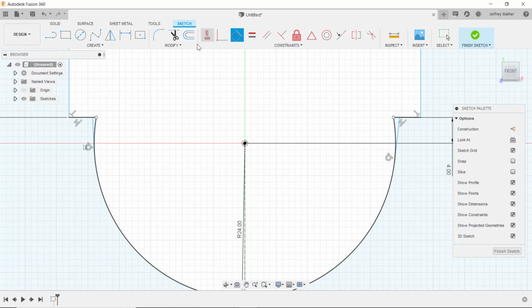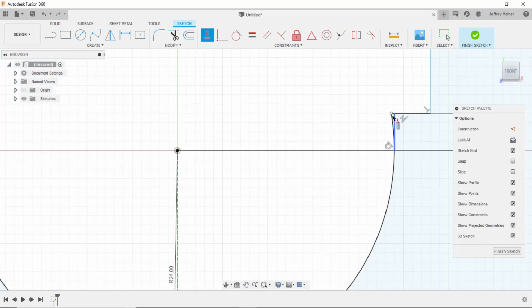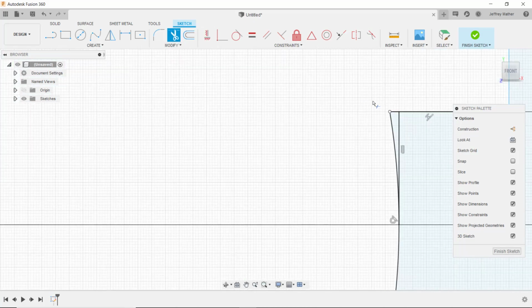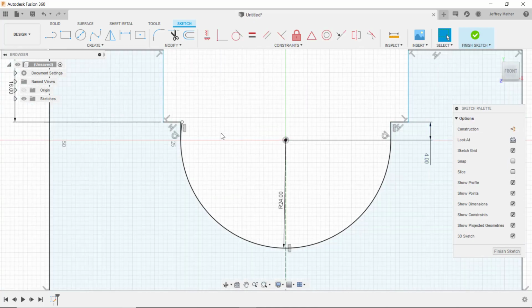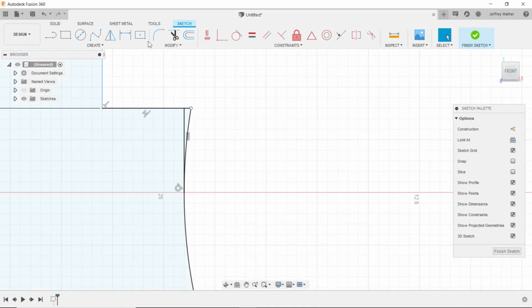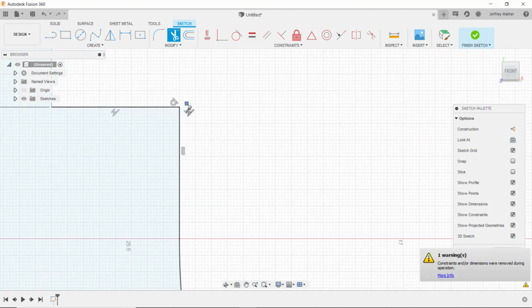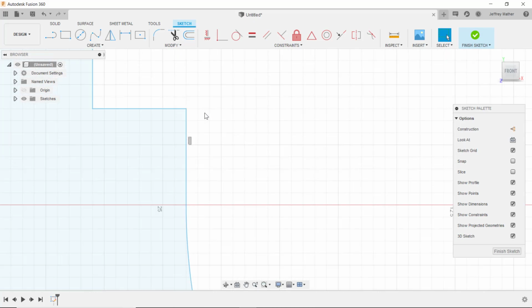And then I want those lines to be vertical, so I want that to be vertical, and I want this to be vertical. And then I need to trim out this little piece right here and this little piece right there. There's some geometry that's left here that I'll delete. And so I see that this turns black on this side. I'll trim it on this side. And I see there's some geometry left over, so I'll do a crossing window, select that, and it's gone.